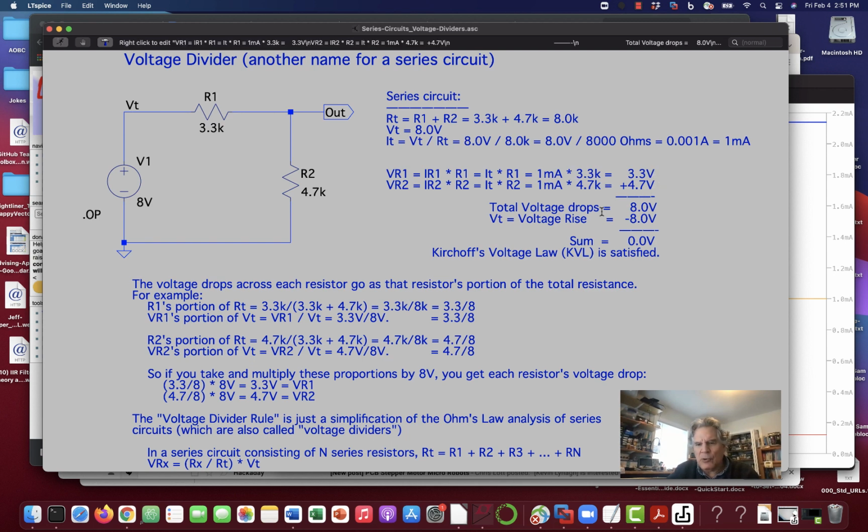And I add up these voltage drops. They're voltage drops because the conventional current arrow would enter where we would write a plus and leave at the minus. Arbitrarily, we would define this as a voltage drop to begin with. Again, we'd have a plus sign here. Conventional current would enter and leave, and that's just the way we drew the circuit. If we put our plus signs and minus signs differently, it still works out. Kirchhoff's voltage law works out, but some of the signs would be different.